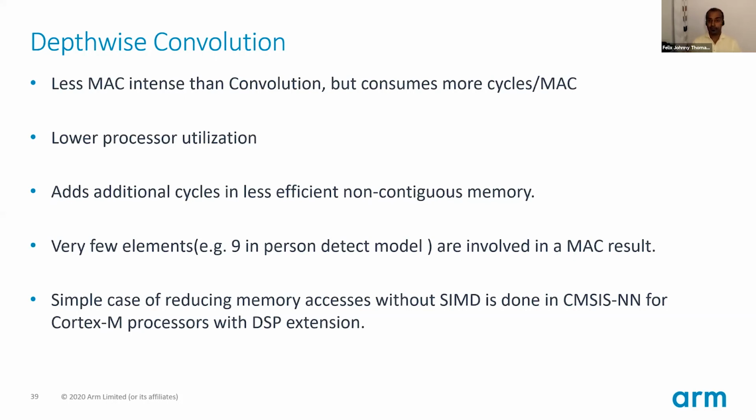And after a while, we had a second pass at optimization, and my colleague tried this time. He removed the SIMD optimization and the image to column method, and was able to get a considerable improvement. At least that was a good lesson for me, to not just tick boxes. Whereas in the case of Cortex-M55, we still have SIMD, where we still have image to column and SIMD methods used for depthwise convolution, and that is still better.